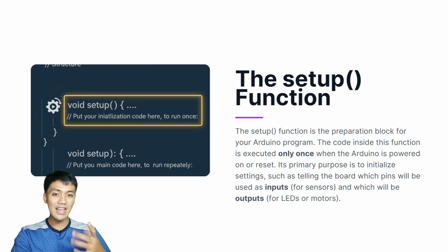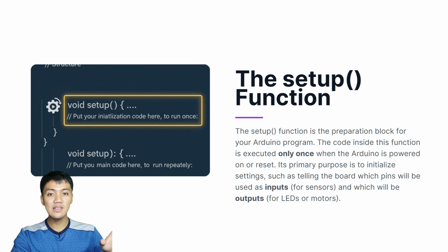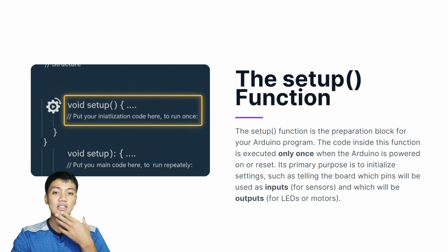After that one-time void setup function runs, the code inside the loop executes repeatedly from top to bottom forever. While the Arduino is turned on, it will constantly and repeatedly read and execute the code that is in the loop function. This endless cycle allows your device to constantly check sensors and control outputs, enabling it to react to the world in real time.